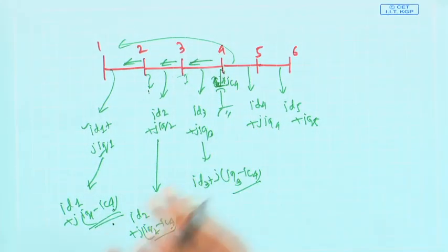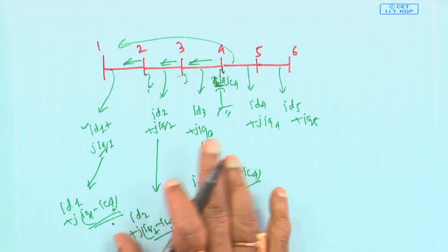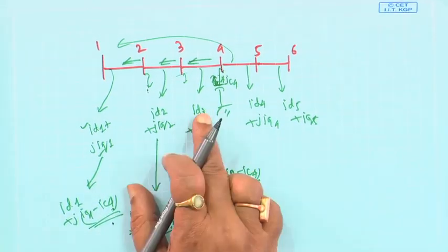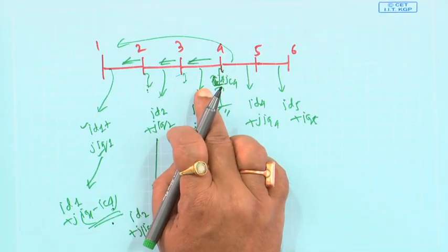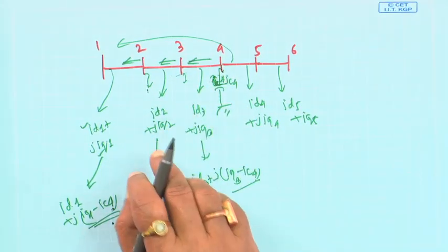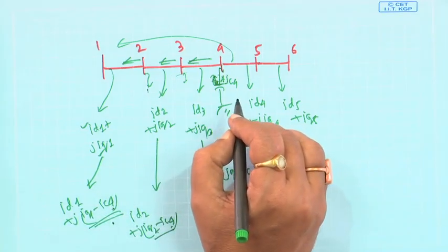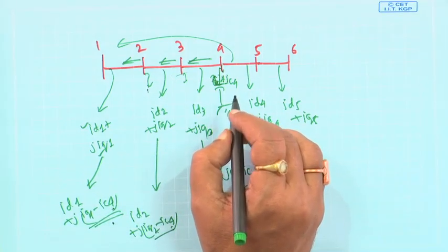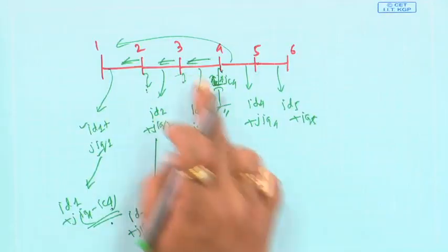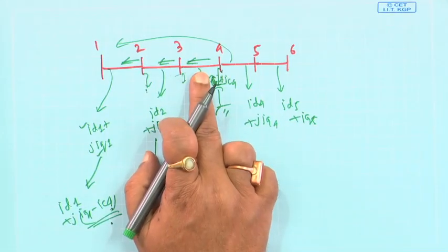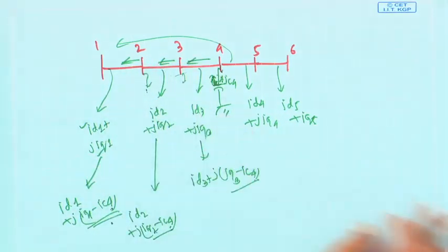This is just the basic thing, before we take a simple example, because in the classroom exercise we cannot show all this without the help of a computer; we need a large network to show it. Only keep it in your mind that the effect of shunt capacitors is local. Local means in the nearby region power loss reduction will be maximum, but as you move far away, the percentage loss reduction will be low. The main purpose of a shunt capacitor is to reduce the power loss, and though not much, it improves the voltage magnitude, because every branch will have less current, therefore less voltage drop. Therefore, to some extent, voltage also will improve.